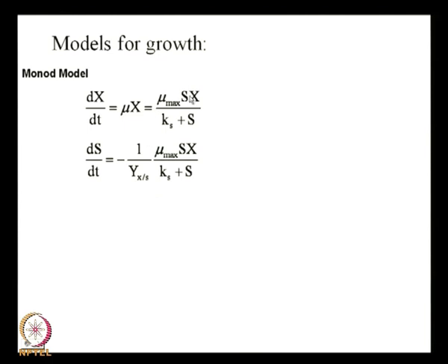So here we have used this as my yield, the reaction rate for x. So you have to convert that into S. If you are doing a molar balance for S, then if the yield of x per unit of S is Y, then 1 over Y is the yield of S per unit x. So you just multiply by that number. Then this is my basic equation for a batch reactor, and what we do now is try to express x in terms of S.